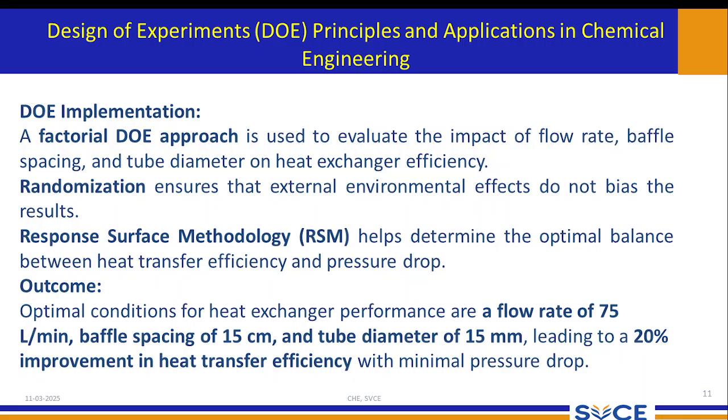Okay, response surface methodology helps determine the optimal balance between the heat transfer efficiency and the pressure drop. So obviously we want a higher heat transfer efficiency, at the same time we want a lower pressure drop. Okay, so the outcome, the output we require, is the dependent variable. The heat transfer efficiency is dependent on the previous factors like flow rate, baffle spacing, and tube diameter. The yield, the dependent variable, depends on the independent variables. The independent variables are flow rate, baffle spacing, and tube diameter.